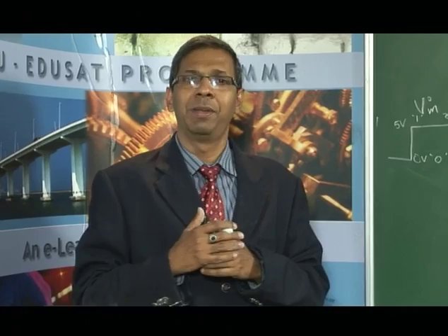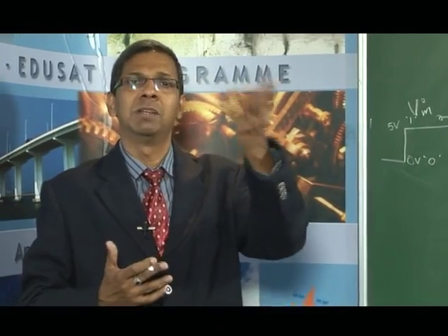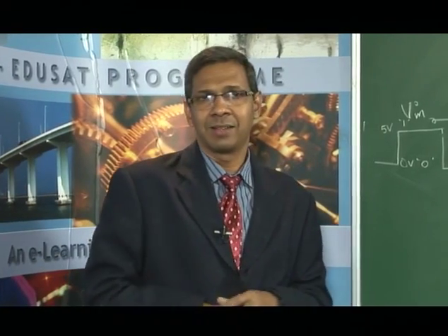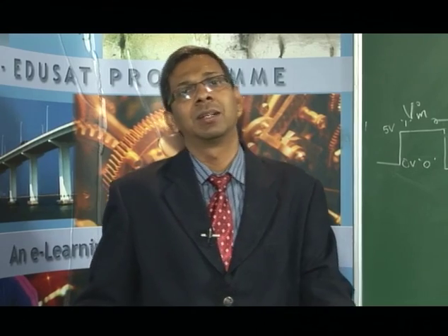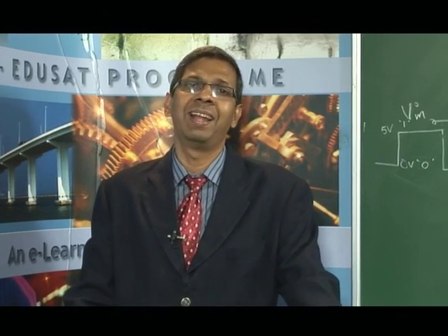So invariably for all the devices you're going to have an equal number of P and N, ensuring that it is a complementary device where NMOS and PMOS complement each other. They take turns to either charge or discharge an output load, thereby ensuring the transition in the voltage level from 0 to 1 volts. This also enables a large packing density.